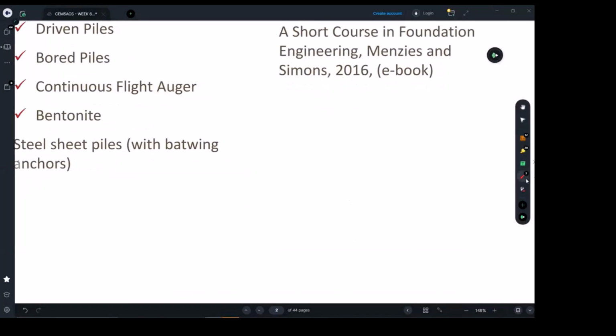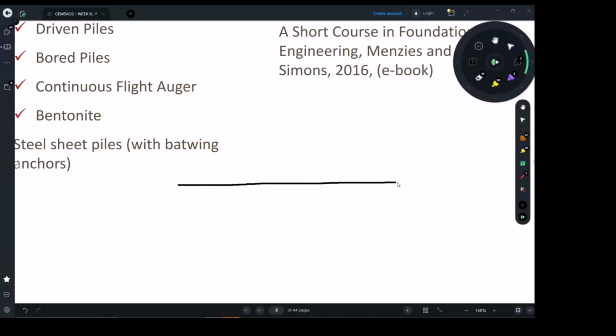Let's talk about the road first. So this is the asphalt road. As per what we talked about last time, on the industrial slab, remember we said when we put our industrial slab, it has to sit on a properly subgraded ground, prepared and compacted, and the soil report will tell us it is a very stiff clay.